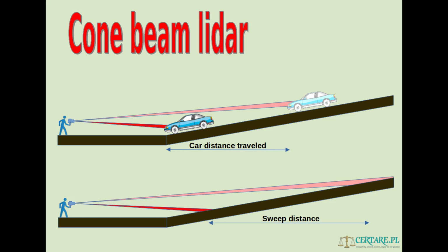Now, if he doesn't hit that vehicle and the beam goes beyond it, part of the beam reads the distance from the road. And why is that a problem? Well, because if he has to slightly rotate or move that lidar to follow the vehicle in order to keep targeting it, the distance being measured from the road also changes.